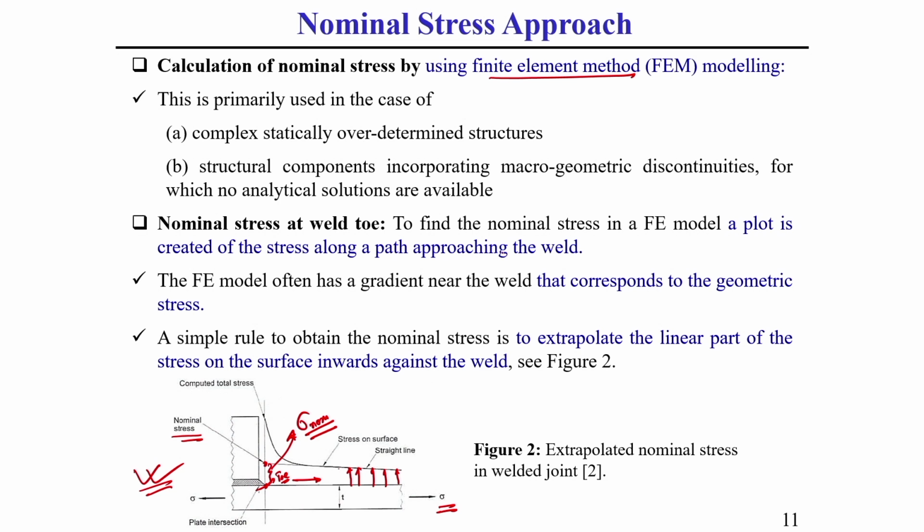To find the nominal stress in an FEM model, a plot is created of the stress along a path approaching the weld.